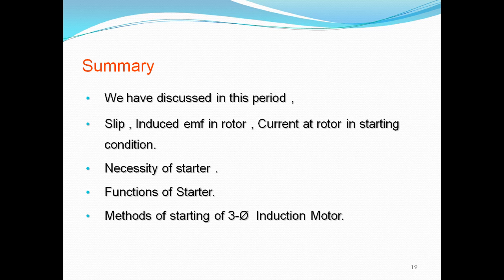When we are adding maximum resistance in series with the rotor, then automatically the current will be reduced. So this reduces the starting current of the motor.